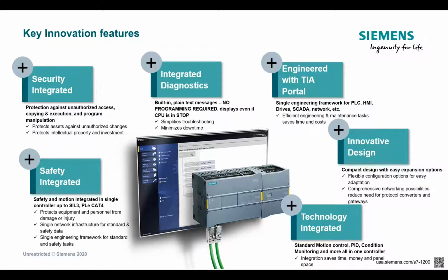There's a lot of different options in terms of different I/O card types, whether you're going to use an I/O board or an I/O card. You can move the I/O rack onto a different row if you don't have enough room. So it's a pretty flexible option in terms of the different things that you can do. And then different technology options, built-in PID. Our PID does have the ability to do auto tuning, motion, VFD control, RFID. All of those are options with the 1200 processor.